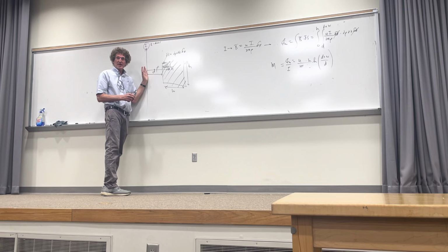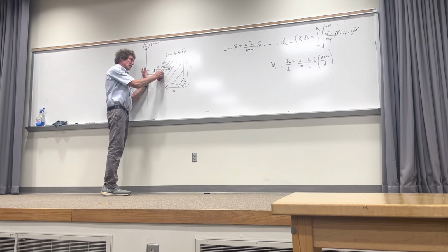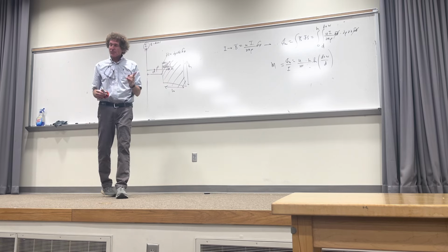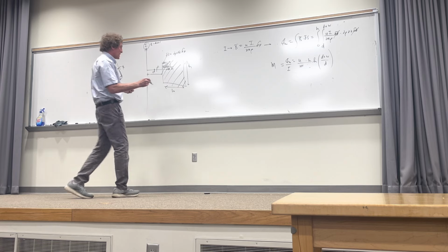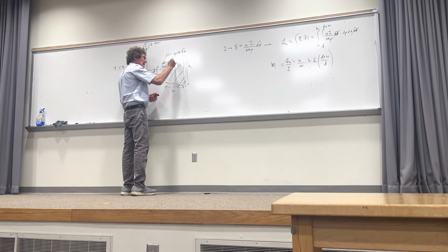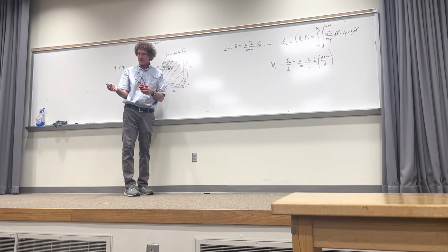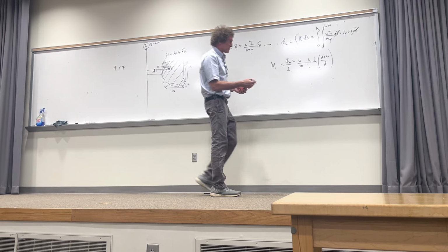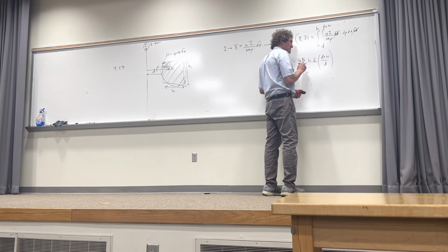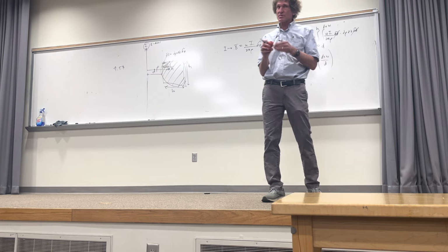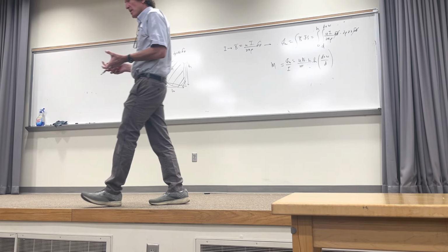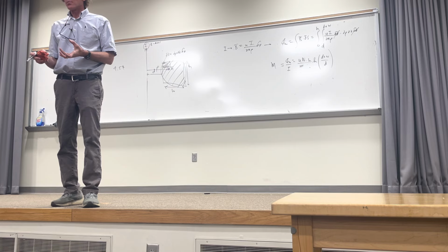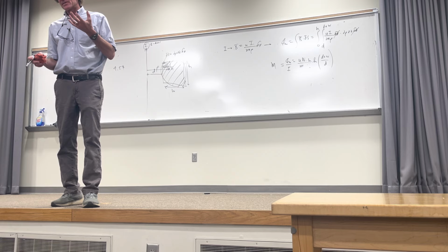Now the thing that I didn't say is there is no such thing as an infinitesimally thin current element. They all have some finite radius to them, right? But the closer you get this to this, the higher the mutual inductance. One last thing, that's for one turn. What happens if I have 2 turns of shellacked wire on top of each other to the mutual? Multiply by the number of turns, right? Technically what I like to do on these things is I'll put in there N, the number of windings, because most of the time when you're dealing with a single coil of wire like that, you're dealing with more than one winding. I mean a single turn of wire. And that's important to realize.